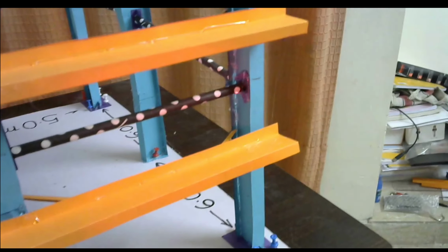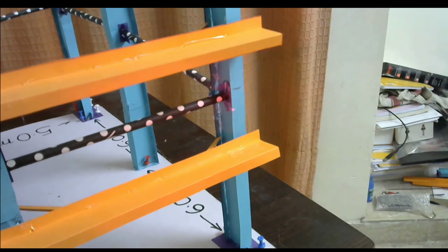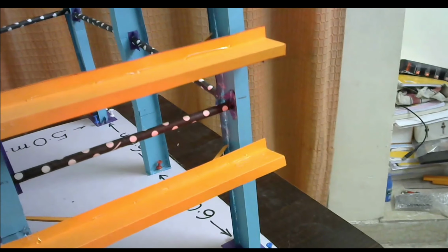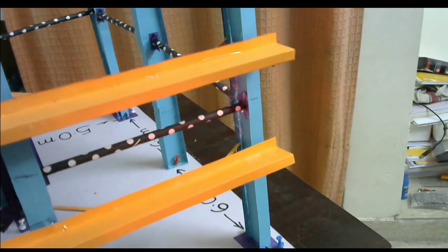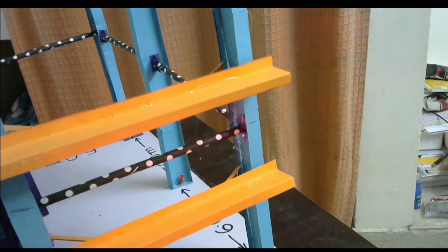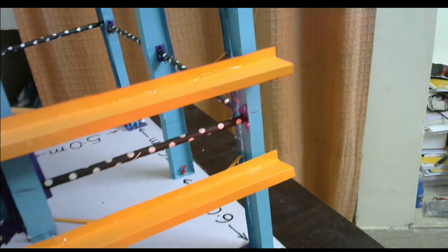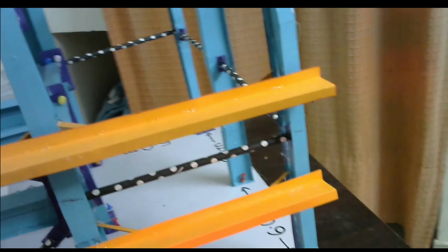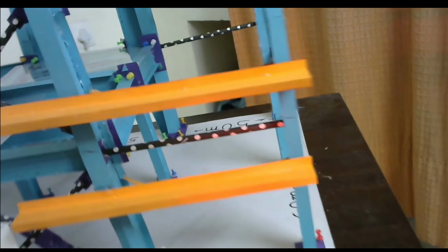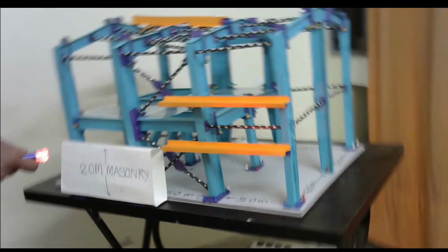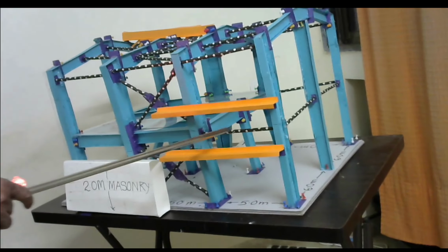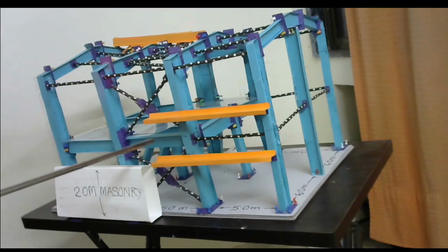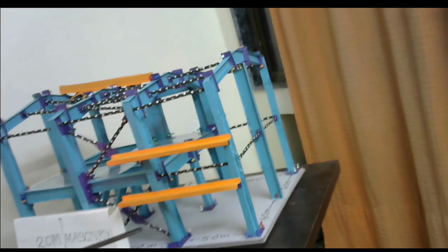Now this end plate is adequate enough to restrain this column. I have already told you that when the flanges are not restrained against warping, when there is a torsional restraint, the effective length factor can be taken as 1. So this remains 1. So LX is 1. Again, by the same analogy, the forces, LY forces will travel through this strut to this bracing and to the foundation.